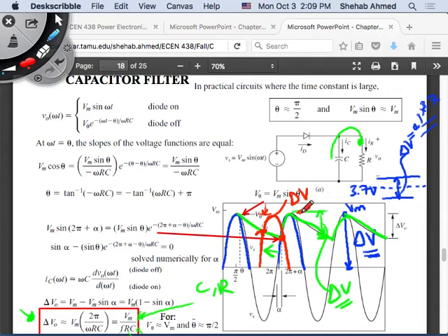That's why in power electronics, people want to use silicon carbide and gallium nitride. Why? It's because they can operate at higher frequencies. You operate at higher frequencies, then you have the advantage of being able to use smaller capacitors and inductors. That's one of the big advantages of the silicon carbide gallium nitride revolution, if you want to say, in power electronics. It's because we can increase switching frequency.